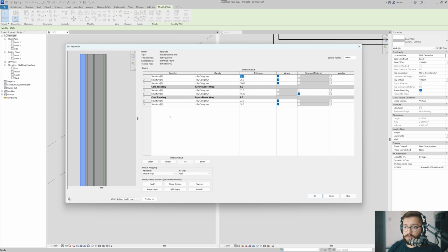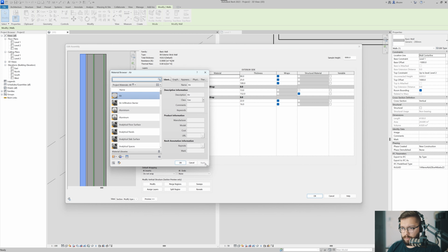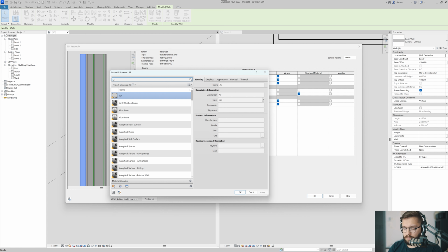The thing is that right now everything's called structure. It doesn't have any materials, and this is why Revit, the only thing it's able to tell me is like, hey, listen, man, your wall is 418 millimeters thick, but there's no properties to it, all right? So let's start assigning materials to it. I'll start from the outside. I'll hit material, and there's these little 3 dots. So this menu would open up, and I would just type in the search bar, brick.